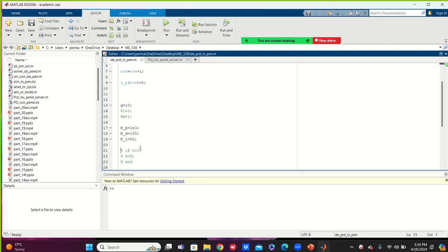Okay, assuming that your actuator is fine, now I increased Kp, Ki, and Kd after the class. And you saw it push the inverted pendulum to 60 degrees. This is the error signal, if you remember, E dot, and this is the I part.